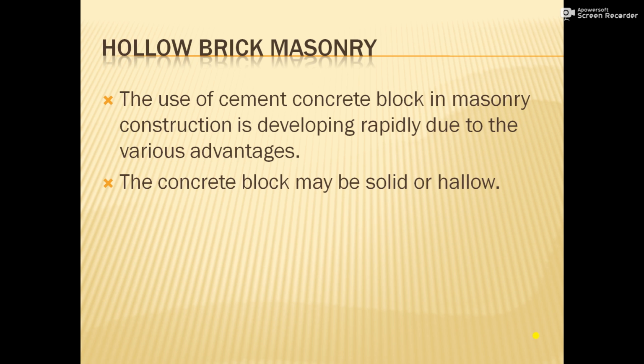So the cement concrete blocks may be solid or hollow. The solid blocks are available in the market with the trade name AAC, when light in color. Cement concrete is largely used for construction purposes on account of its numerous advantages over other building materials. The hollow units may be defined as those units which have core void area greater than 25% of their total areas. The blocks shall have their water absorption less than 10%.